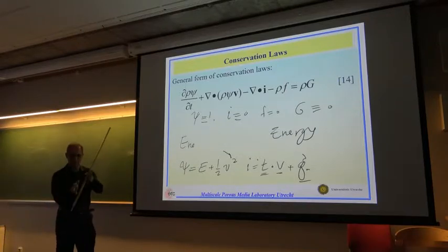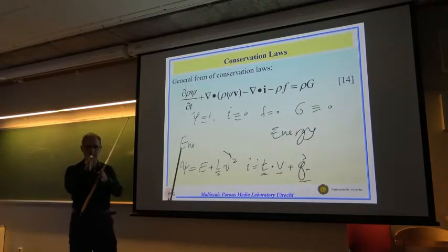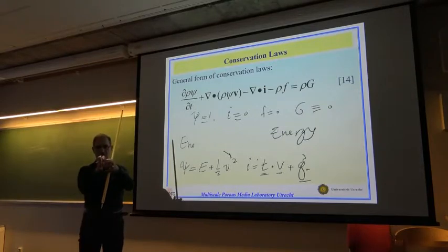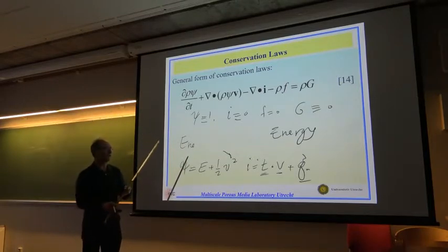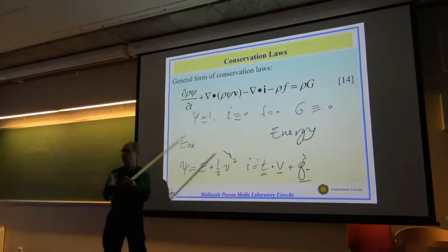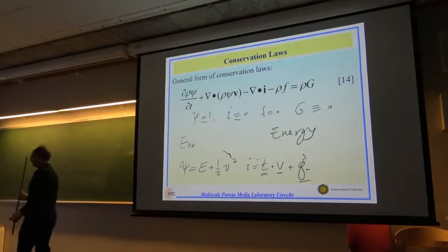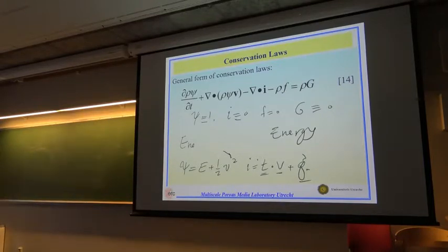Because if you have an imaginary surface within the body, because of the stress tensor, the contact forces, if there is movement, the contact forces will transfer energy to each other. And then there is a heat transfer which is occurring even if there is no movement, that's the transfer of energy. And then from the outside world, we will have gravity working if there is velocity, and then you can have radiation.